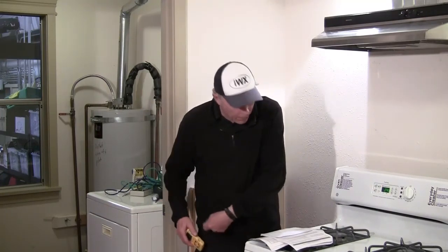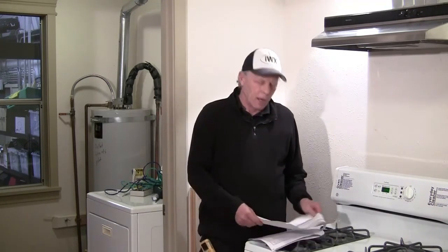I also want to pay attention to my ambient CO, and I have 0 ambient CO, which is good. But if you do have ambient CO, you need to make sure that you know where to find the action levels on this BPI sheet. It happens quite often that we get CO in these test houses during the oven test.